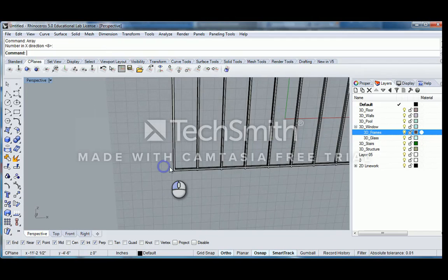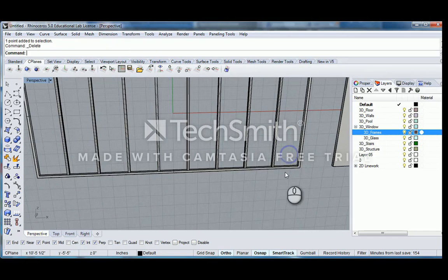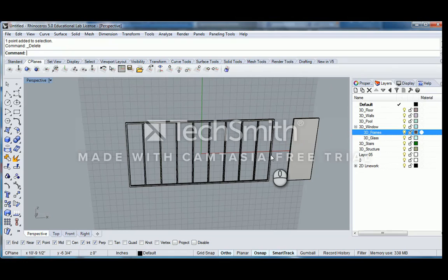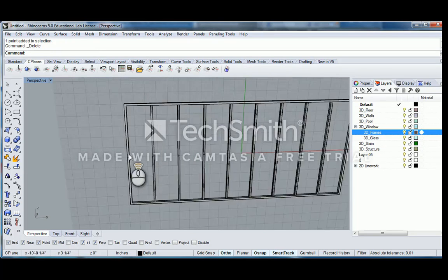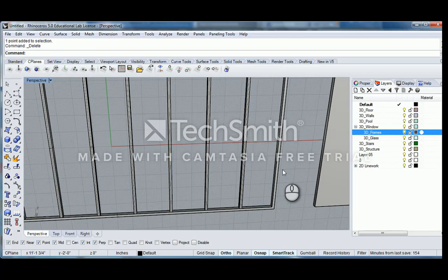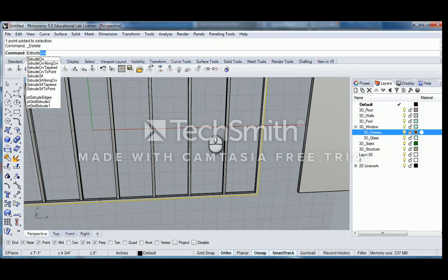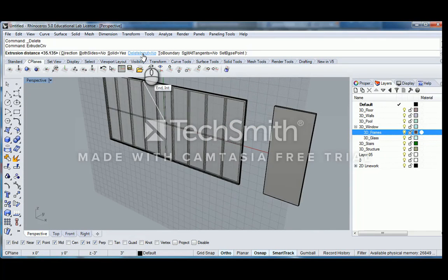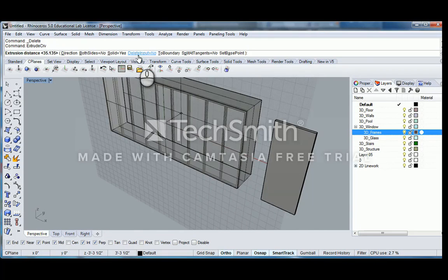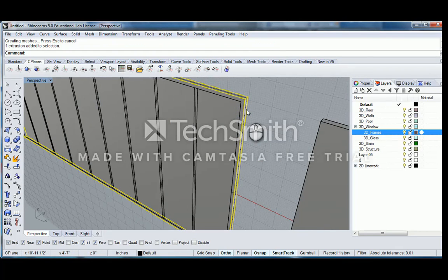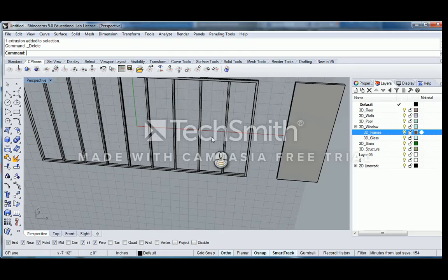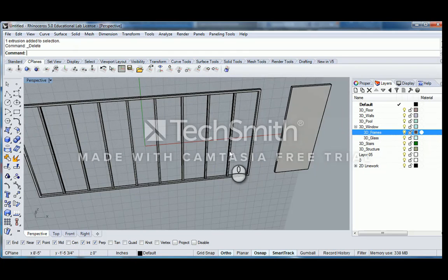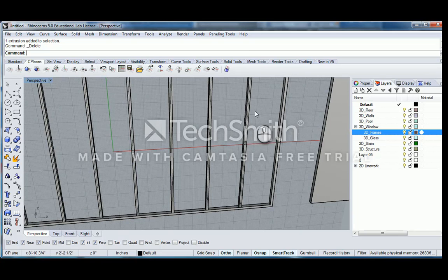So you know how you did an extrude command on a surface, but there's still the lines that you have to delete on the outside of the surface? Is there a way to automatically delete the input? Basically where if I click extrude. So I've kept delete input as no. If I extrude this now with delete input yes, that line is now gone, and I just have the solid. So that's the way to keep it kind of clean. Again, sometimes you want those reference points to propagate in the future, but that's the quick way to delete that reference geometry.